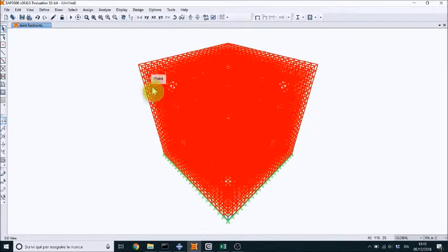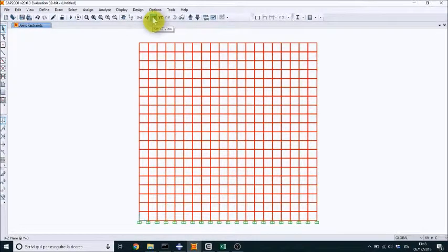We have to assign lateral boundary conditions on each face of our soil. Again, we can assign restraints for this first example, so a fixed condition on each node. Pay always attention to the right direction. Now we are in the z-x direction and y is equal to 0.